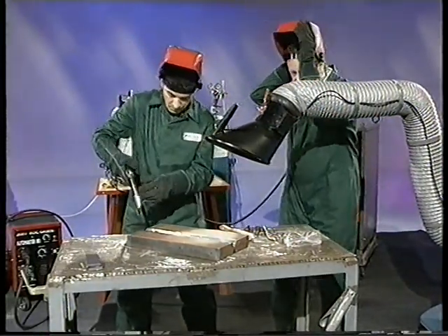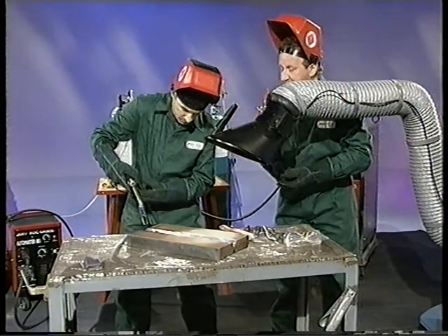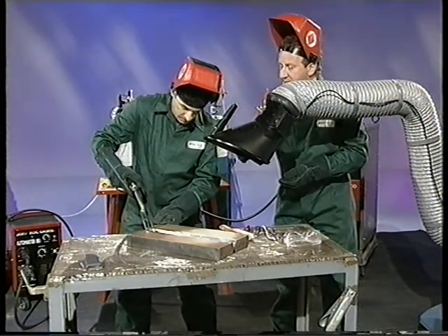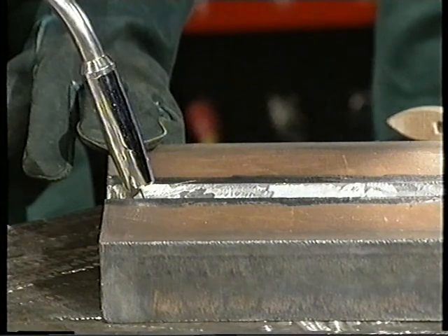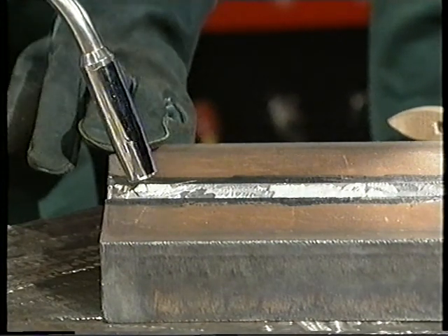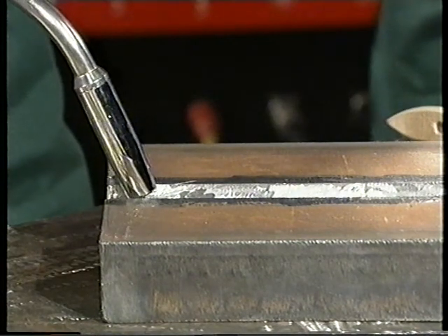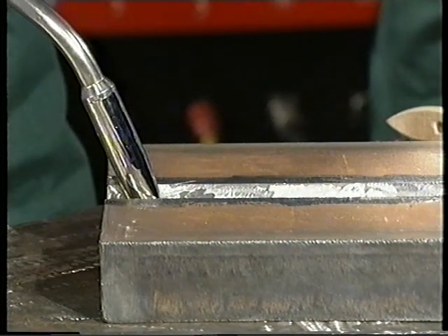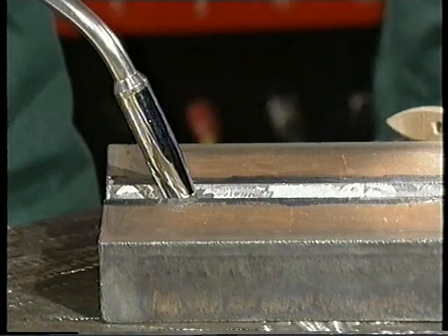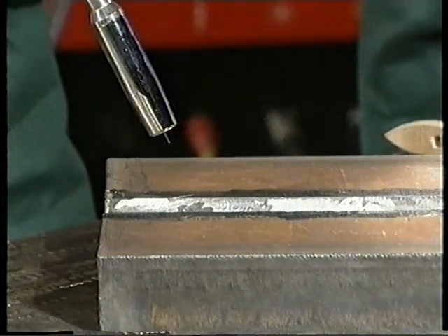What about angles, Mel? The same way as you did before, Steve, moving from right to left, holding those torch angles the same. But this time, increase the stick out, maybe have about 25mm stick out. You want to spread the weld on both sides of the plate. You probably won't have to weave in this first pass, but later on up the joint, you may well weave to bring both sides of the joint together.